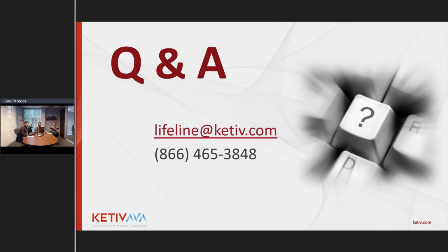Definitely. And another thing with the LM tools, I don't know if you covered this, Jose, but for the 2017 license files, to be able to read a license file with 2017 software on it, you need a new version of LM tools. Yeah. And that version's 11.13. That came out in like February. So if you did download your LM tools before that, you're gonna have to install the new version in order to get your license manager to read your 2017 software. And it is included with the 2017 software.